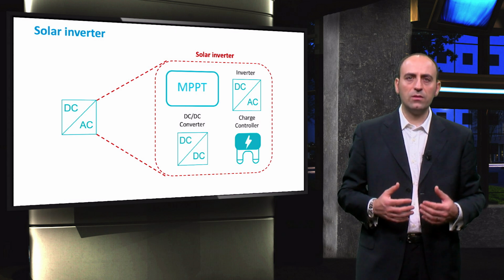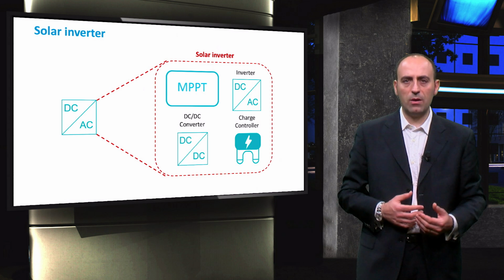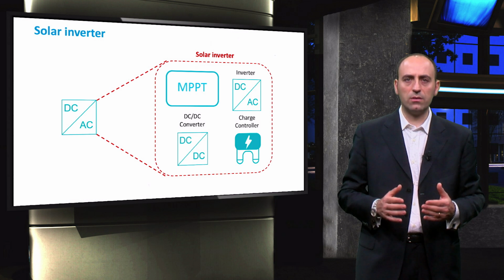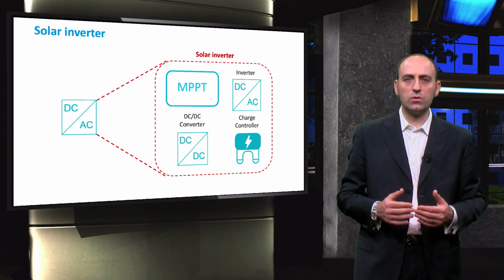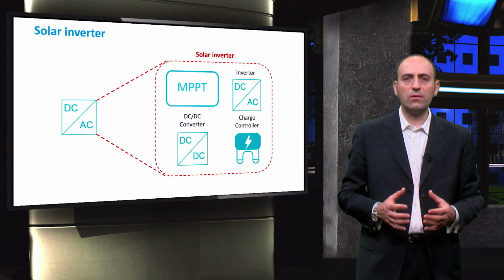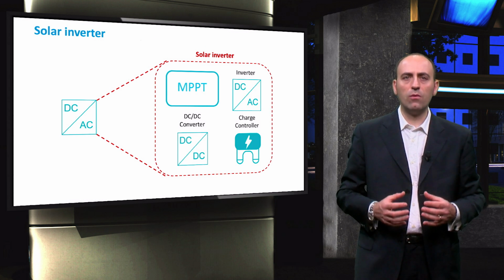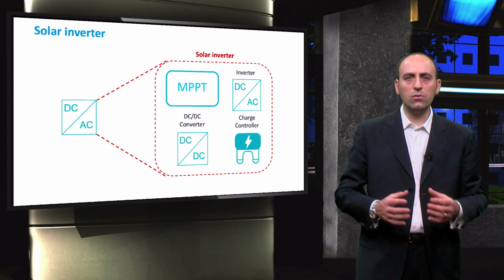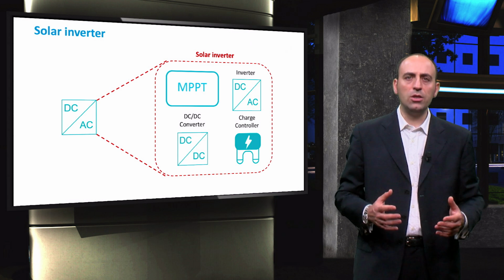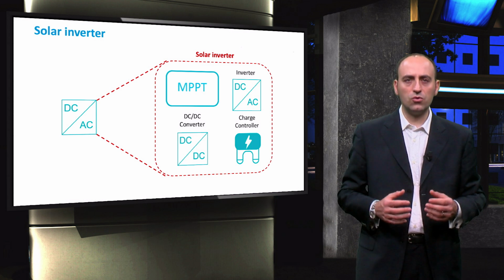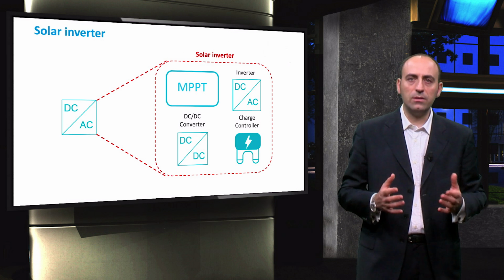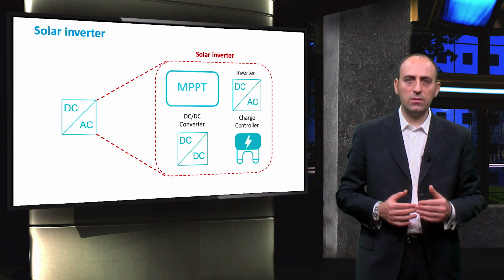Indeed, in an inverter, DC power is transformed into AC power, but the DC input voltage of the inverter is always constant, while the output voltage of the module set, at the MPP, is not. Therefore, a DC-DC converter is used to transform the variable voltage from the panels into the constant voltage seen by the DC to AC inverter. Additionally, the maximum power point tracker controls the operation point of the modules, but cannot set it. And this is also done again by the DC-DC converter.